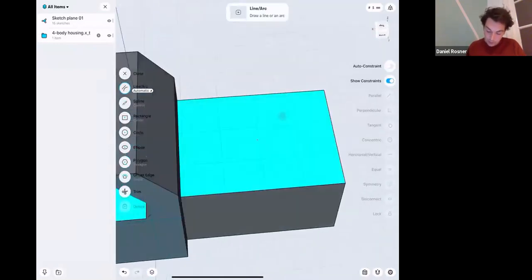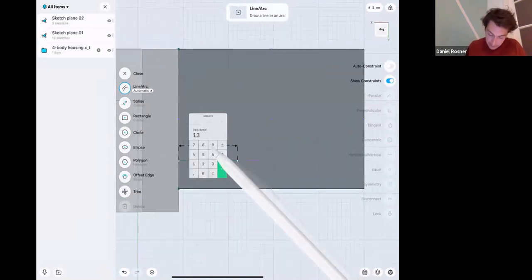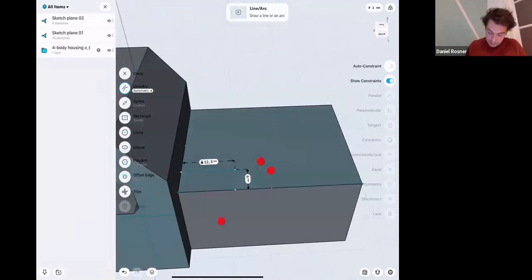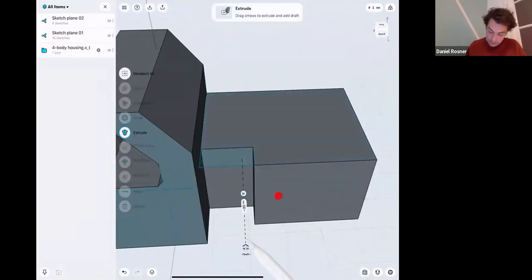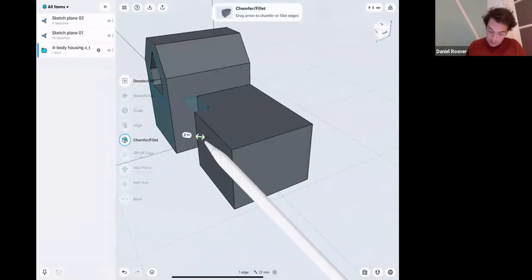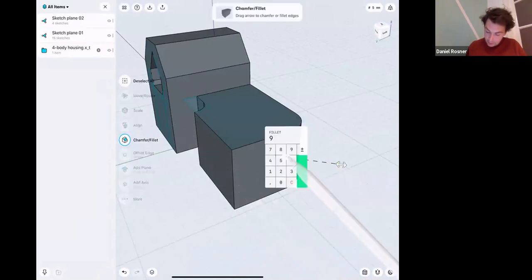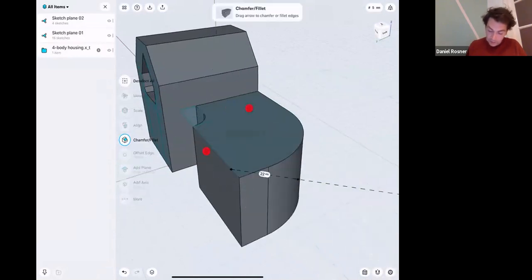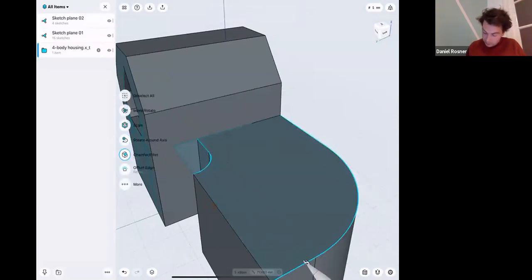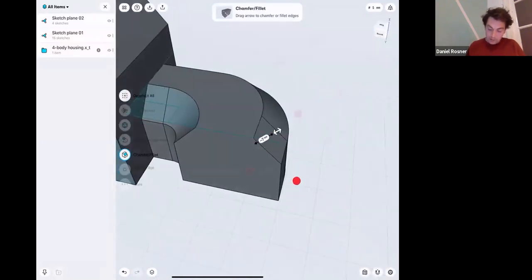And now I'm going to go to the second part, the second mount. I'm going to remove first some material, which should be 0.5 and 6. Great. Let's remove some material and add a fillet. I'm going to start adding fillets now. This should be 6. Let's add a fillet here as well, which should be 22, and add some chamfers as well. Again, add fillets as much as possible to ease the stress on the corners. This should be 7. Great.